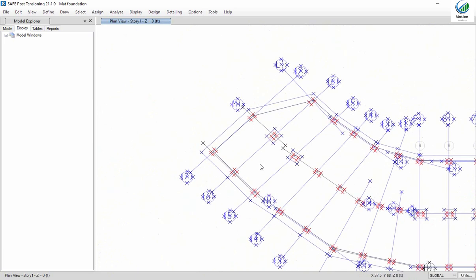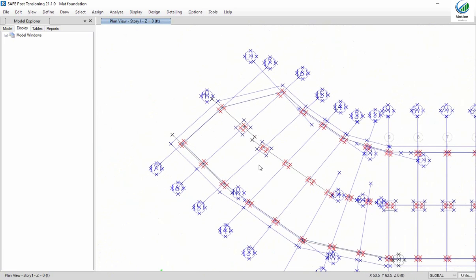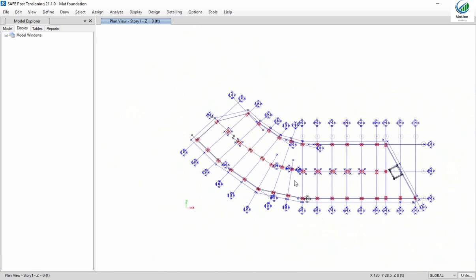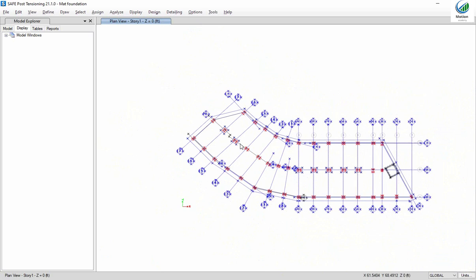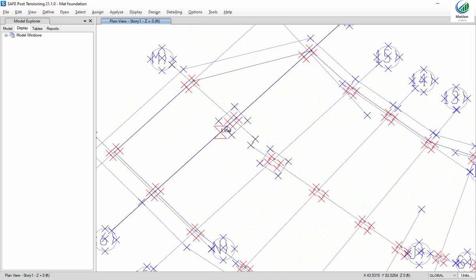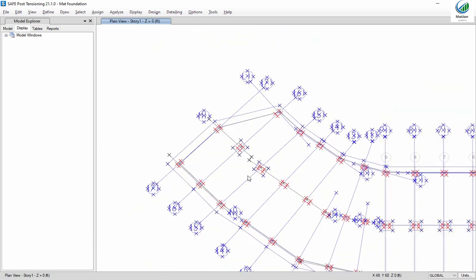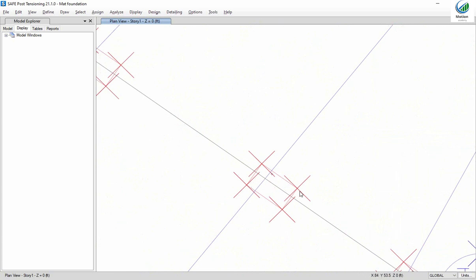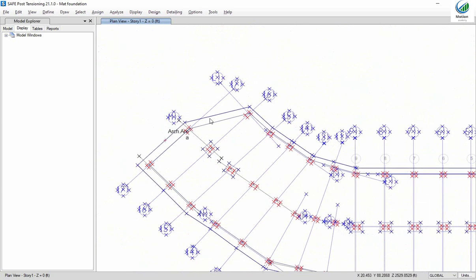So it is very important to make the coordinate system accurate, which we discussed in the part 1 lecture videos. Now our reaction forces are already imported into the SAFE model, and our foundation geometry is also imported. Now what do we have to do? Now we will draw columns and slab in this particular segment shown in the shaded area. For example, this is a column portion and the whole portion is the mat portion.